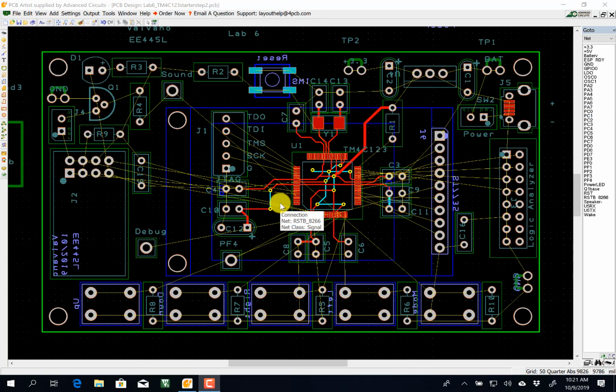All right. Some time has elapsed, and I have placed all of the components onto my PCB. The green line here represents the size of the board. And you can see I placed the drill holes in the corner. I've placed these switches on the back side of the board, which will be on the same side as the display.